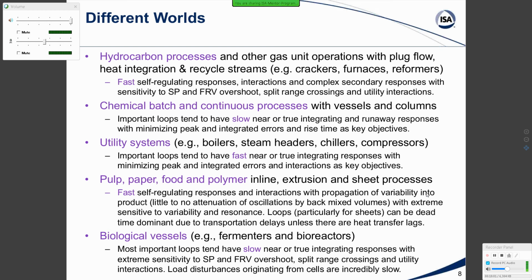But the big problem there is a lot of noise and difficult measurements. In fact, it may not be a representative measurement, and the process dynamics can get very weird. In fact, it may not be identifiable, and it can even change the process gain, and the gain can change sign. And so Michelle Ruel actually reverted to some fuzzy logic control. But it is a challenge due to the difficulty of the measurements and the noise and sometimes the strange behavior in the dynamics for mineral processing.